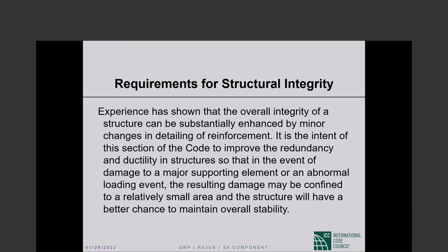Yeah, I know. I'll just go over a few of them. So I will start with the question on torsion first. Okay. So for a four-leg stirrup, say four 12 legs, can we assume the outer leg to transfer the torsion and inner two legs to transfer only shear? No, not only shear. All four legs will carry shear. Outer legs torsion and all four legs shear.